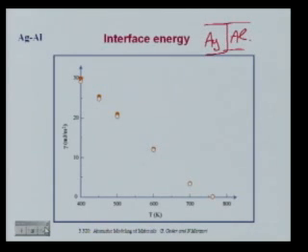You can get a hint from the fact that it's getting a lot smaller with temperature and actually kind of goes to 0. What would happen to that interface as you heat it up? I think you know. You're just afraid to say. Diffusion, yeah. It interdiffuses. Silver and aluminum are somewhat immiscible at low temperature. But when you heat it up, silver and aluminum interdiffuse. They actually don't form a full solid solution until you're way up, but they interdiffuse.